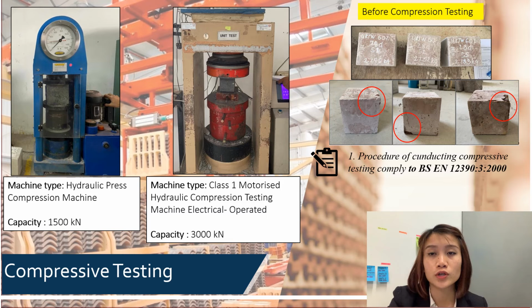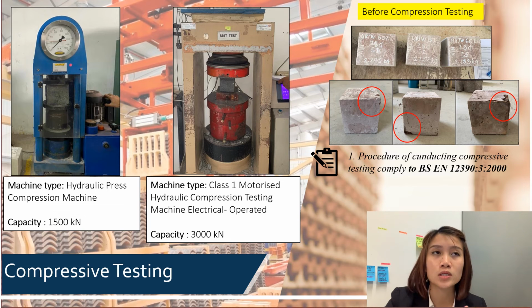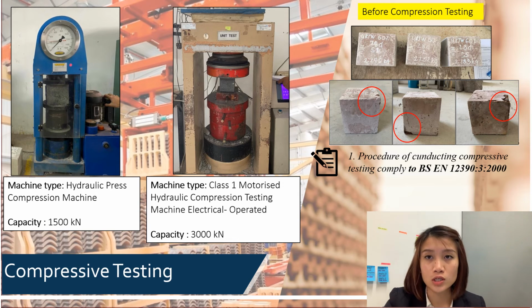The reason for using 2 different types of machines to test the concrete cube is that there were circumstances that couldn't be avoided, but luckily all the 28 days concrete was tested using only 1 type of machine. Mostly all the data and analysis for the concrete focus on the 28 days, because in the British standard, the procedure for conducting compression testing focuses on the 28 days.